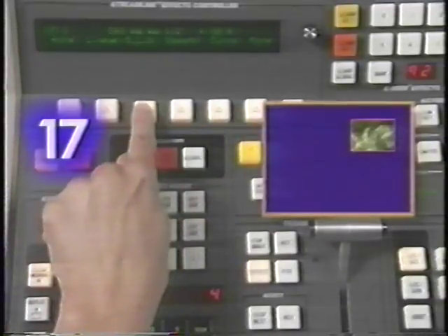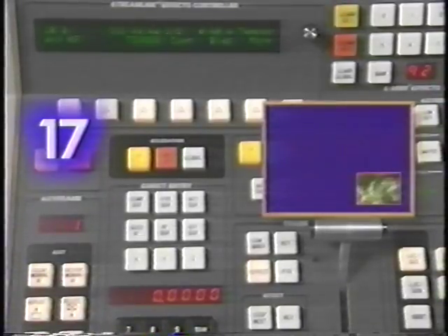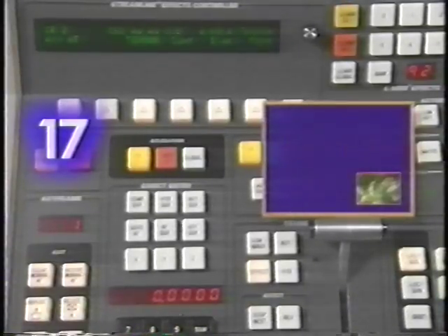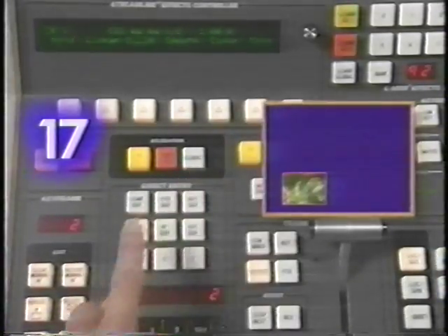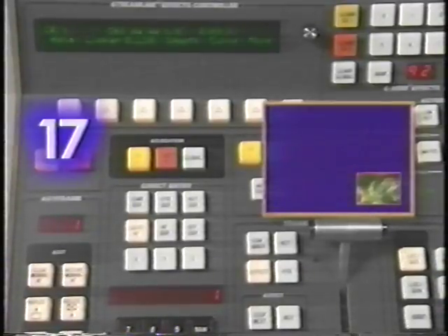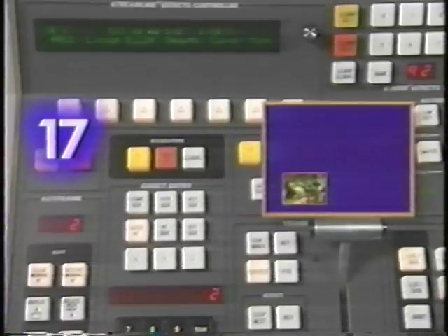Select S-linear and then press All Keyframes in the same menu. This will cause the location and center of orbit parameters to change in an S-linear fashion for every keyframe in the effect. Rewind and run your effect. Notice that S-linear in-betweening does not have the bounce effect that linear in-betweening has. Go to keyframe number 2. Select Hold and press Replace. This will cause the location and center of orbit parameters to change instantaneously at keyframe number 2. Rewind and run your effect. Notice how the instantaneous parameter change at keyframe number 2 differs from the S-linear change at other keyframes.